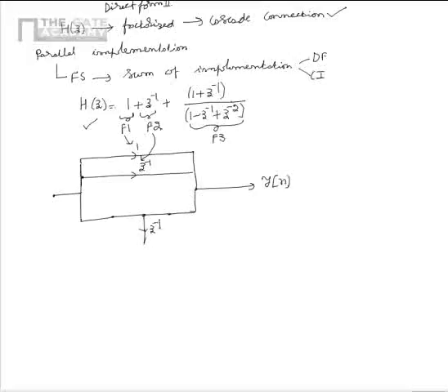Here there will be two delay elements Z inverse, and as already mentioned the coefficients on the right hand side correspond to the numerator, so there is a weight of 1, and the coefficients on the left hand side correspond to the negative value of the denominator, which would be 1 and minus 1. So now we realize the direct form implementation of filter F3 here. So let the input be X of n.